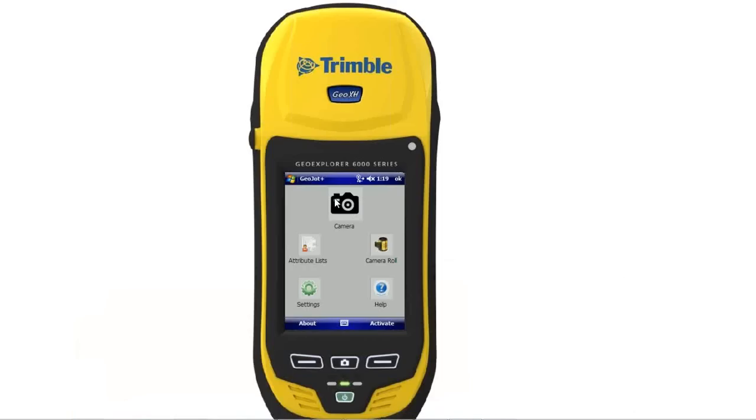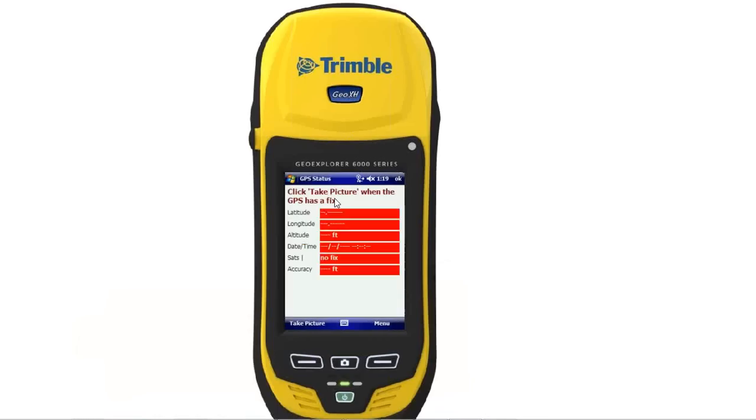I'm going to go back to the app quickly here and show you a few things. On the app, when you go into the camera, there are a couple features that we've added here. You see on the camera screen you've got your latitude and longitude data, as well as the amount of satellites you're tracking and an estimated accuracy. One of the things we've added for the Windows mobile version is the point averaging feature. So if you click that, it'll start counting up the amount of points it's averaging. And if you're in a situation where you need to have a certain amount of average points before you take your photo, it's really easy to do from there.